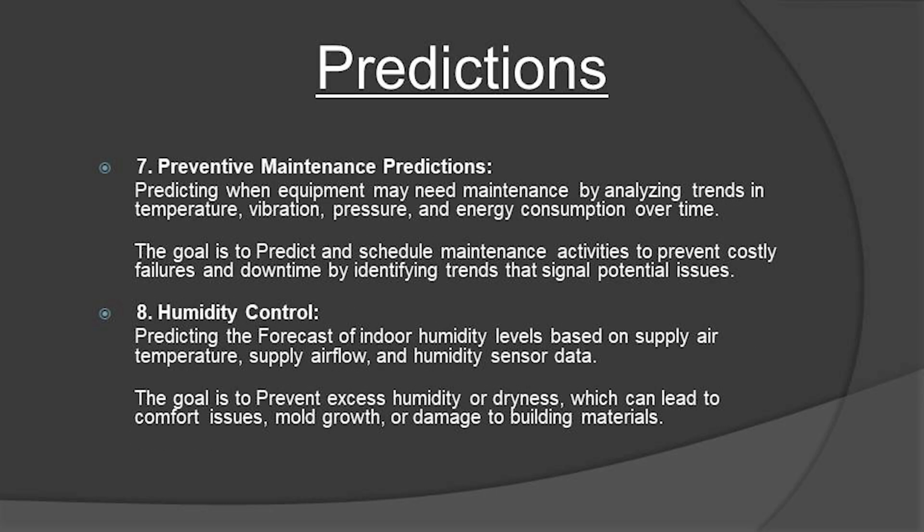Preventive maintenance predictions. Predicting when equipment may need maintenance by analyzing trends in temperature, vibration, pressure, and energy consumption over time. The goal is to predict and schedule maintenance activities to prevent costly failures and downtime by identifying trends that signal potential issues.